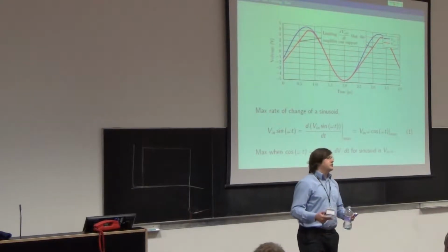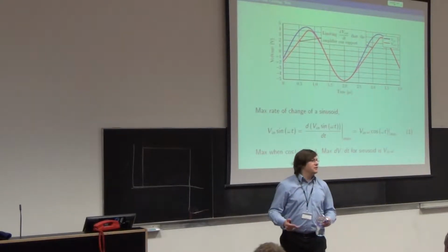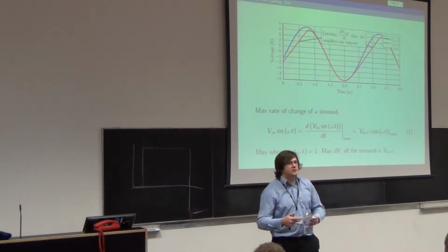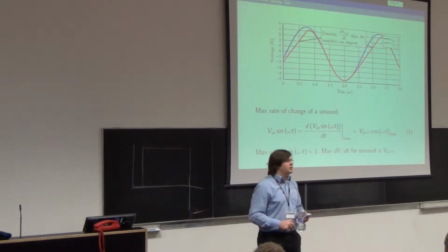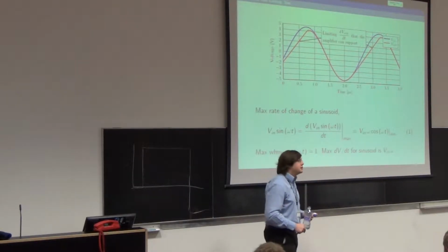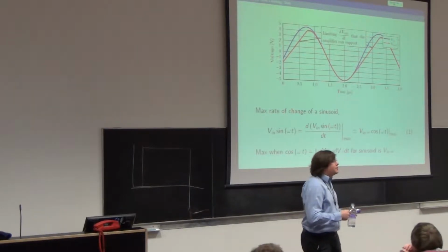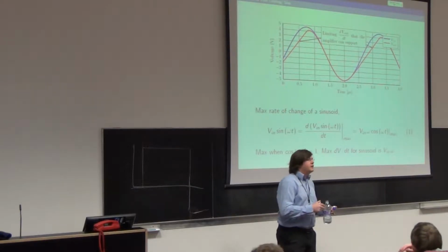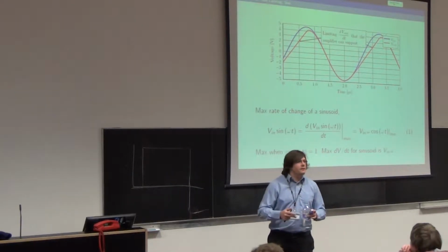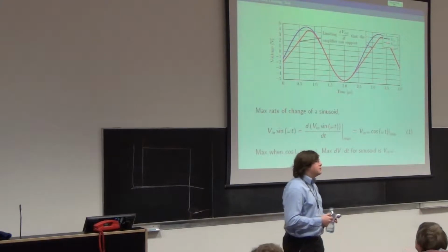If you want to make an audio signal, it's the end of the world, because 20 Hz to 20 kilohertz is the human hearing bandwidth approximately, as long as you don't go too much to the extreme. So the bandwidth of your amplifier and its slew rate are kind of together, but they are not the same thing.